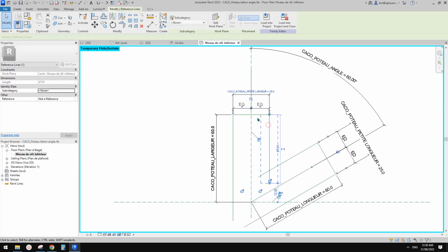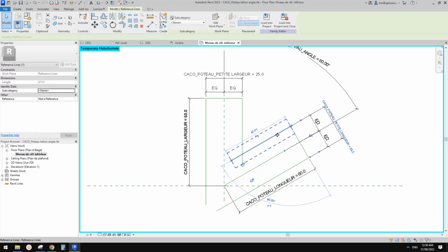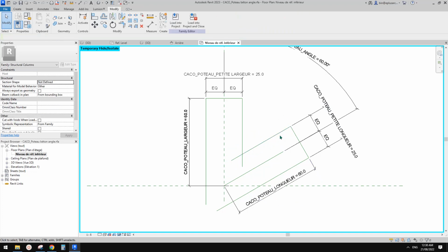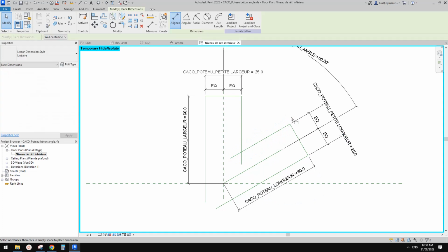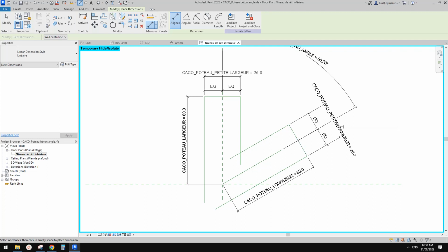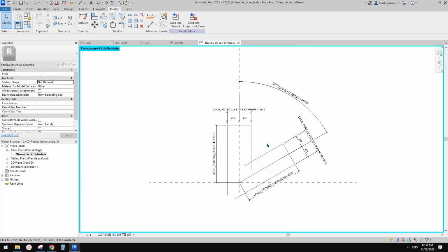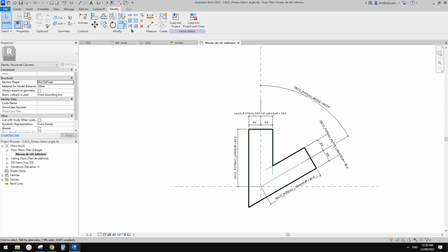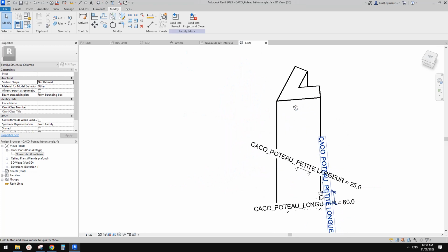Yeah, I think it's probably that the dimension was placed onto something else; instead we should dimension on this reference line. So if I do a DI, you should pick this line and this reference line. So maybe that dimension was placed onto, for example, this point instead of the line. So yeah, I think that's probably why. So now HR, I think it's all good.